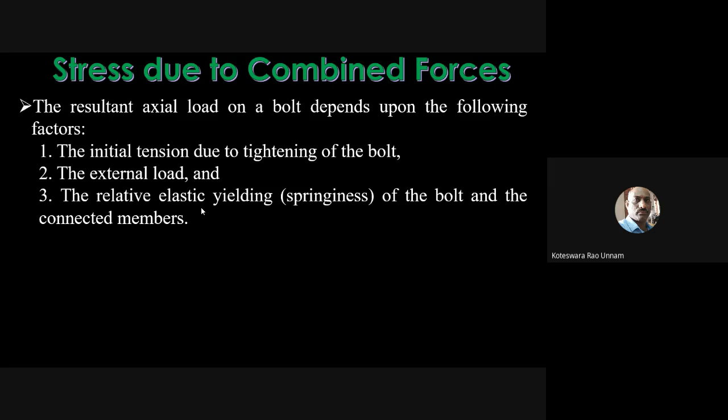Okay. So the relative elastic yielding of the bolt and the connecting members: the springiness or stiffness of the connecting members will also influence the resultant load acting on the bolt. In our bolted connection, you are connecting two members through a bolt and nut. So whenever an external load is applied to this connection, the total external load is not taken by the bolt alone. The connecting members will also take some amount of load. Therefore, I cannot take the total external load as the load on the bolt; you need to consider only a fraction of it.